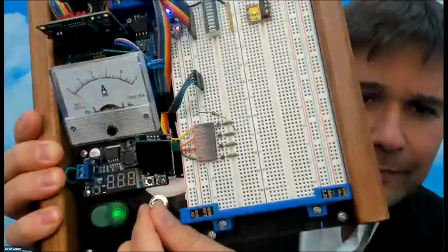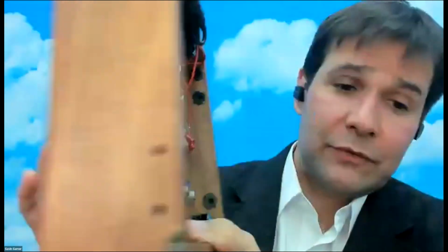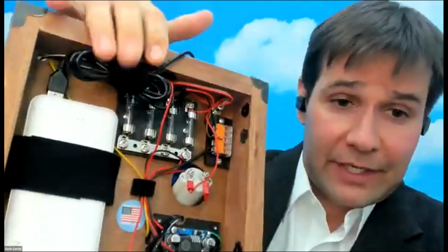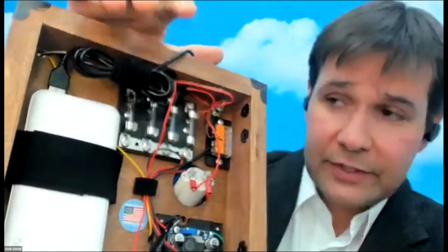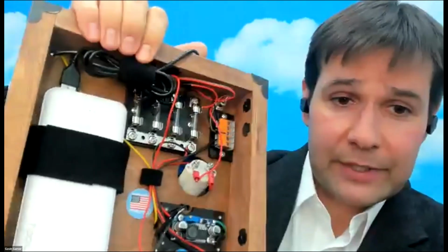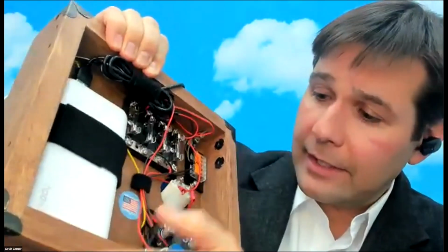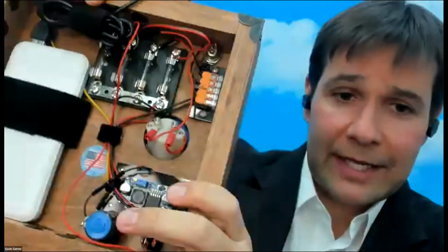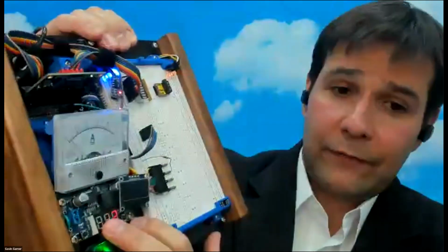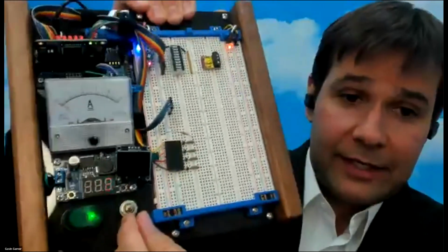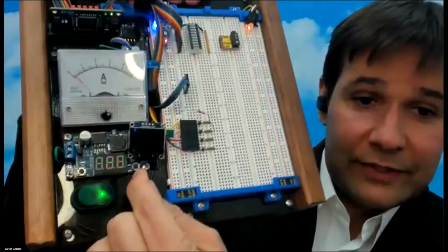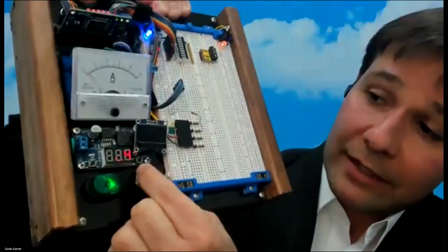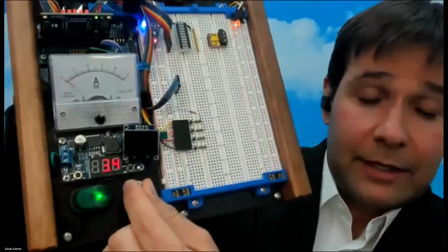So I tried to go really cheap and use everything running off of 5 volts on this thing. I've got fuses, big fuses that are easy to replace, and students do blow these up occasionally. And I've got the 5 volts going into a boost converter, which boosts it up to about 12 volts. That allows them to use a buck converter on this side, which has a nice display. And that's coupled to this extra potentiometer that makes it very easy to adjust the voltage coming out of the power supply.